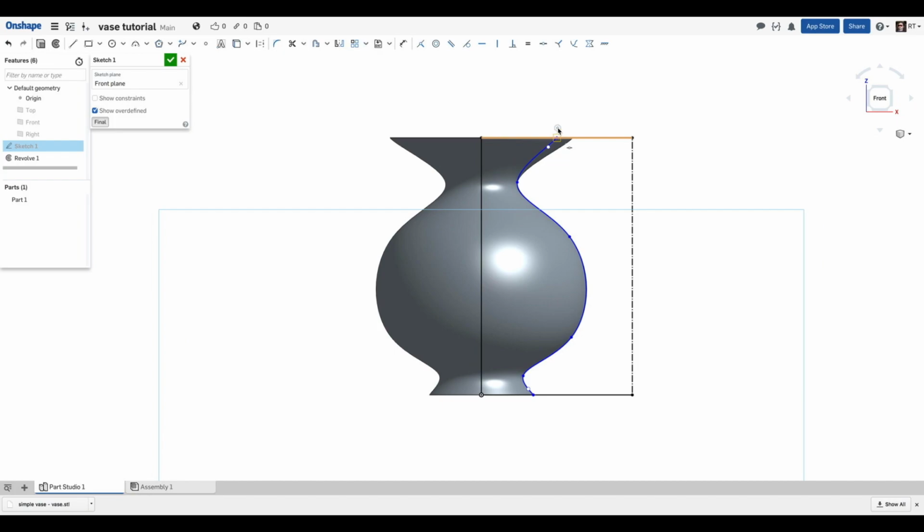Careful when you're moving across the center here because it wants to snap to that center point. If you hold down the shift key, it will avoid that. It's already constrained along this line since we ended that point. But if you hold the shift key, it won't try to snap to any other points. If you let go of the shift key, it'll try to snap to that corner point, or this inside point, or the center point. Or potentially if your mouse is close to this, vertically above that point, or vertically above this point.